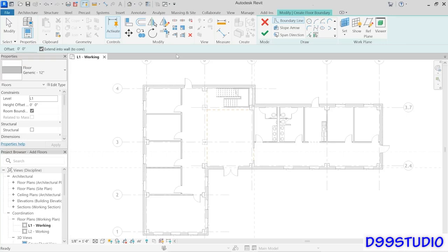Now, what is sketch mode? Well, it's got some pretty noticeable characteristics. The first is that the drawing window grays out and becomes kind of halftone. Okay, so that's one clue that we're in sketch mode. The next is that the Modify tab of the ribbon is now tinted in this greenish color. And then perhaps the most noticeable feature of sketch mode is the presence of the cancel and finish buttons right here. And those buttons are used to get you in and out of sketch mode.